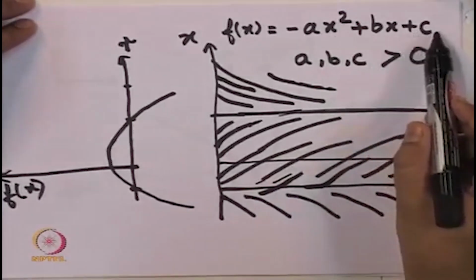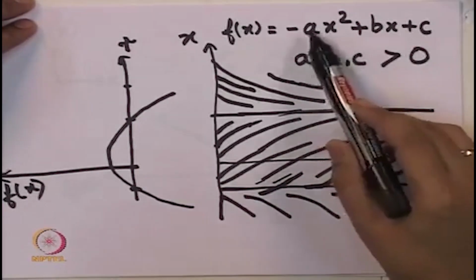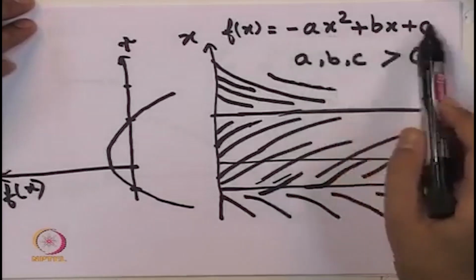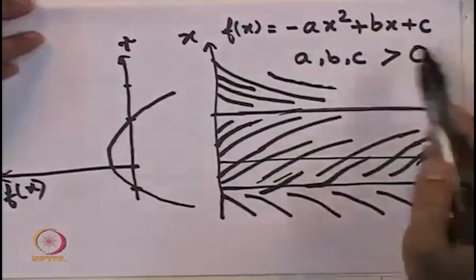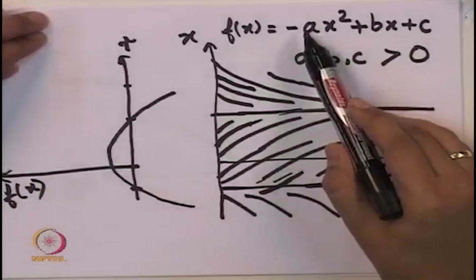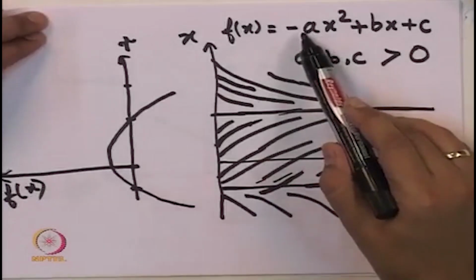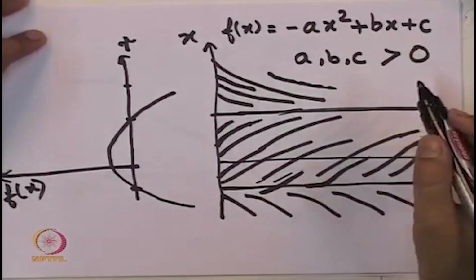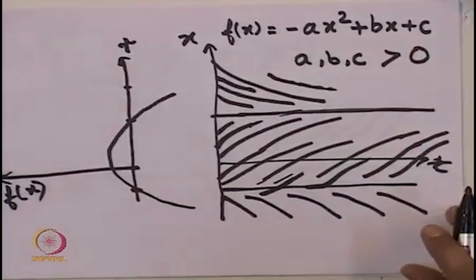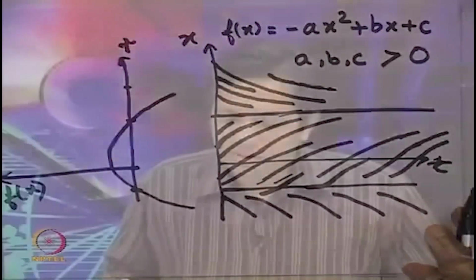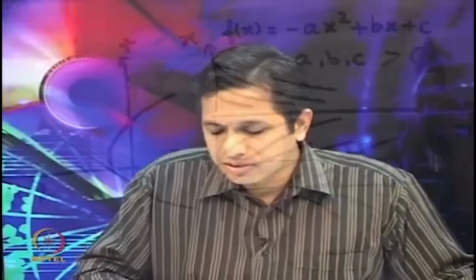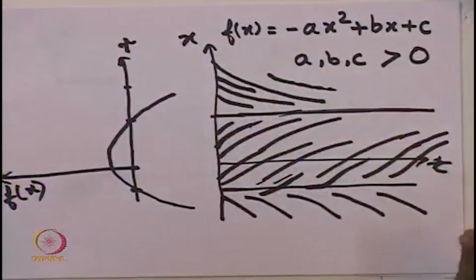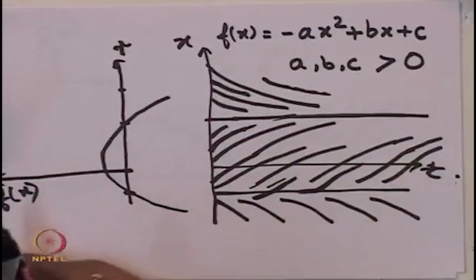Because this particular quadratic equation with the leading term negative and the leading coefficient and the constant having opposite signs is a situation we encounter in the Kalman filter case. In the continuous time Kalman filter, in the recursive solution, we encounter a differential equation that has these particular signs. Of course, this is for the situation that the state variable has only one component x.